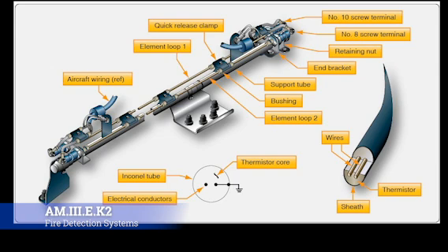All right, so the thermistor's core resistance decreases as the temperature rises due to fire or overheat. The control unit applies 28 volts DC and detects a change. Reaching an overheat set point triggers a delayed warning, so it's going to heat up and say, "Hey, look, we're overheating," and we're going to give it 10 seconds to see if it's just a flash or if this is a sustained fire. While a further drop, at the fire set point, activates an immediate fire alarm system.